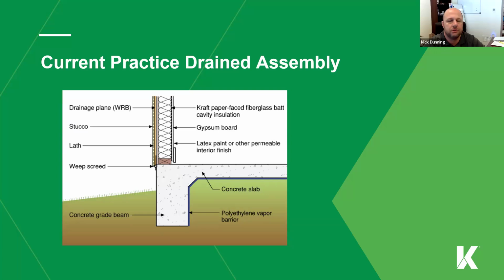Keep an eye on your mulch too. A lot of times this is designed assuming, sometimes, unfortunately, that the architect will design it without any landscaping being there. But even when they do it properly, a lot of times mulch isn't removed, plants grow, their root spaces go up a little bit, and they will actually elevate that. But as Hector shows on this drawing, if you're above where we've actually done our subgrade waterproofing, stucco is not a waterproofer, it's a weatherproofer.